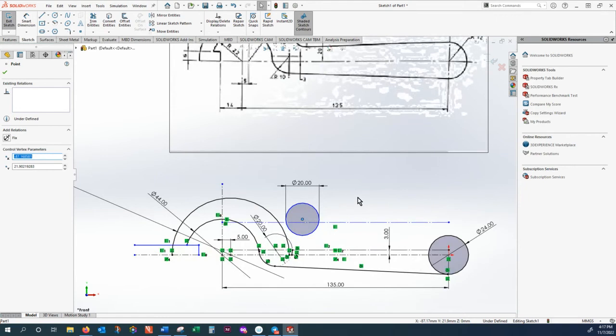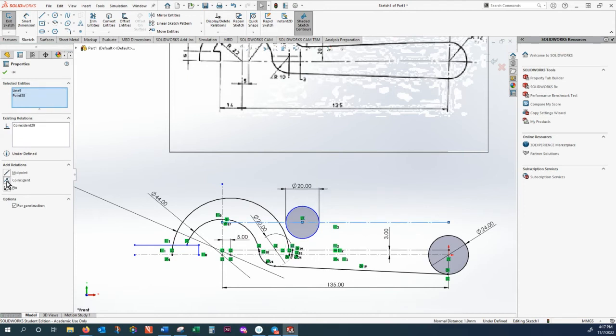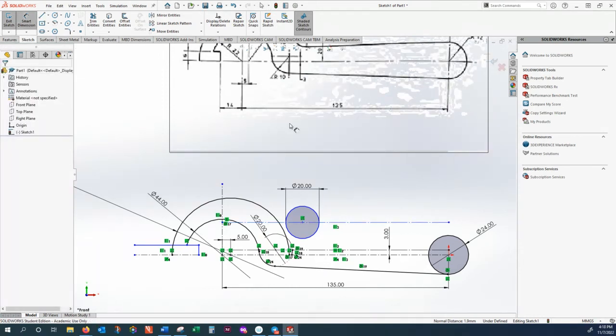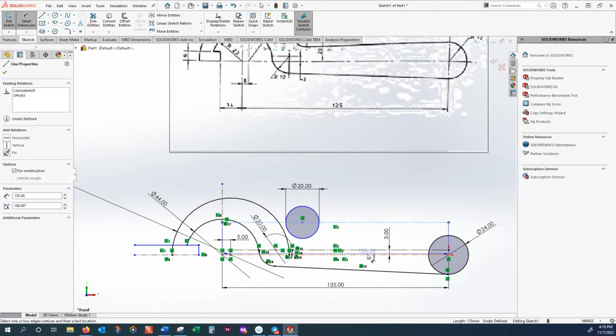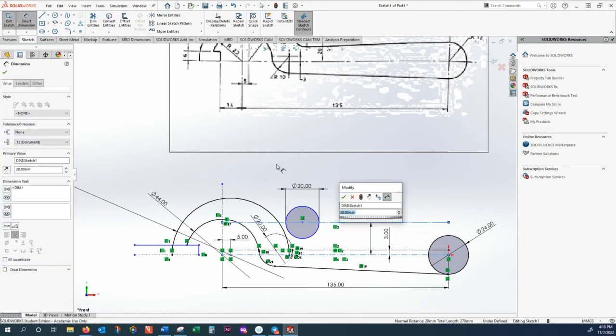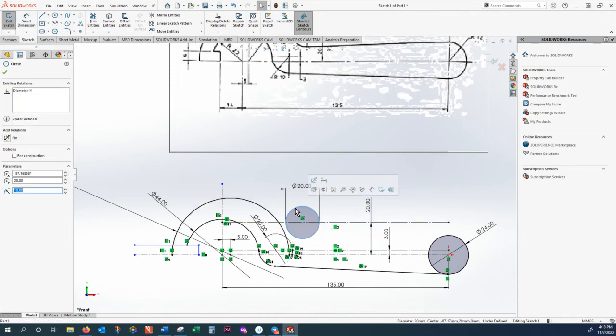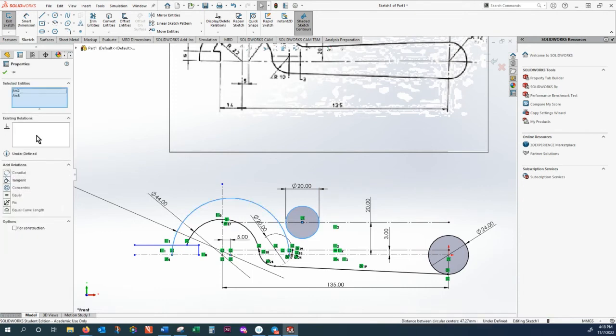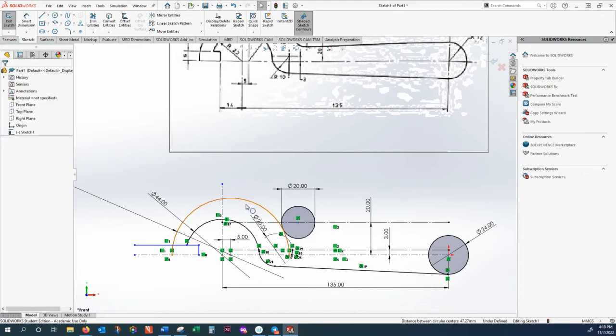Okay, couple of conditions. First, that point being selected, select this line and make them coincide. And to prevent this offset to change, it's a good idea to add a small dimension to that. 20, and then this arc has to be tangent to this arc. Select, hold shift, this one select, make them tangent. So I'm not sure, yeah, this one is fixed.